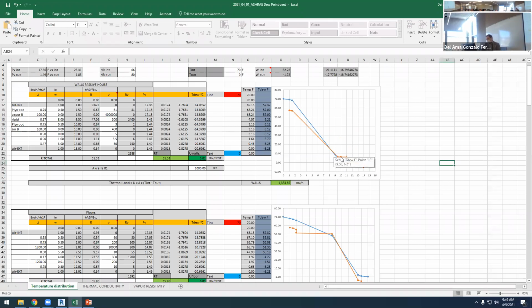As you can see, we reduce the condensation risks. And even if it happens, the rigid insulation can bear the water, so it's not affected by water. All the fibers, the glass wool, the rock wool, the cellulose, they are affected by water. And if they don't get dry immediately, they will stop being a thermal insulating material.